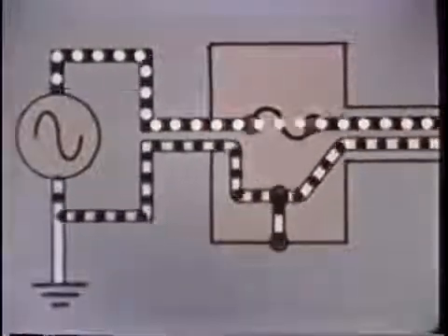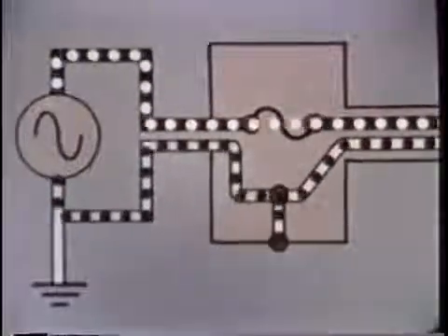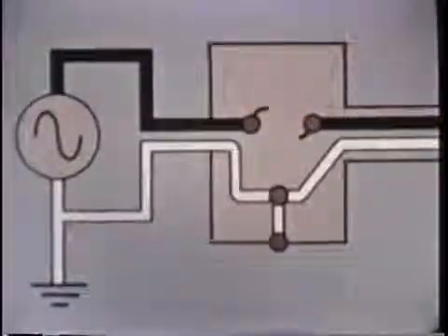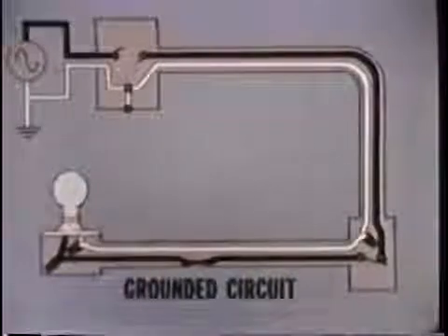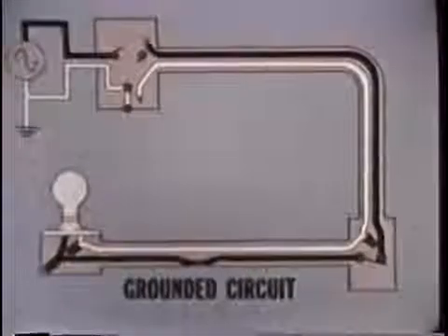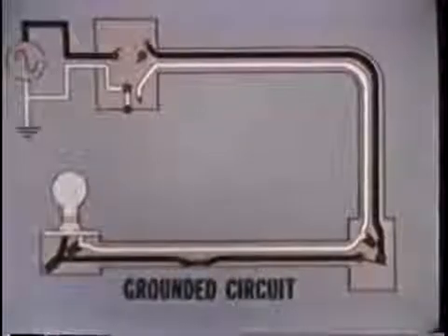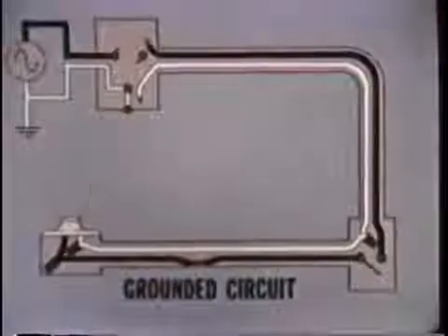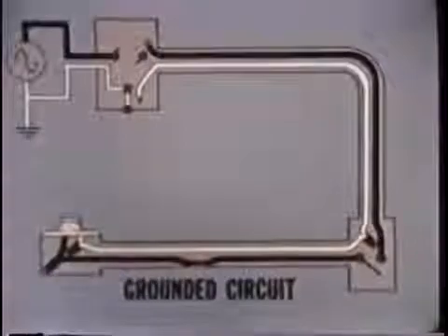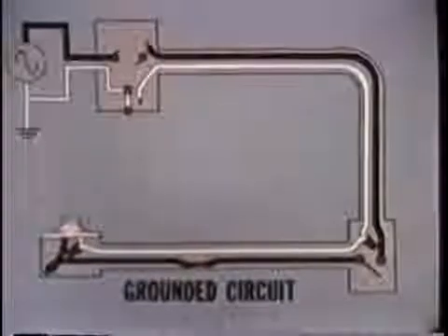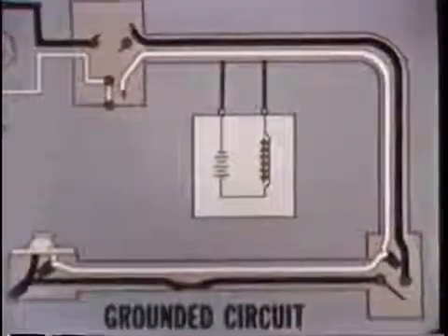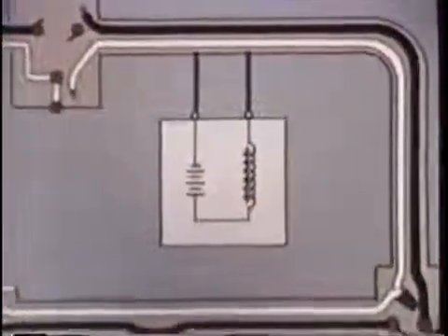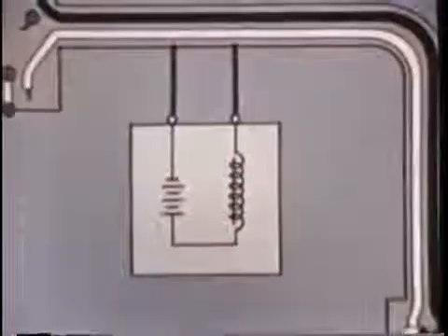Let's examine another case where we come on the trouble site to find a blown fuse. Once again, to deal with the circuit safely, remove the wires from the power source. Remove the other elements in the circuit by opening the switch and removing the bulb. This time, instead of using a multimeter, let's use a buzzer-type continuity tester. This tester is simply a small door buzzer and a dry cell battery.